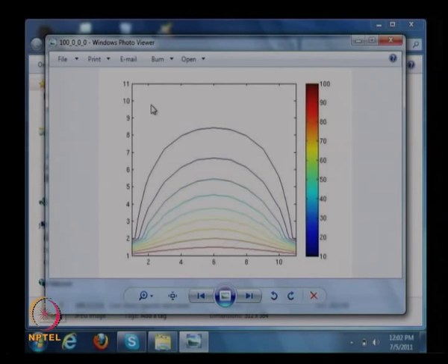So this portion of the slab has almost reached a temperature which is between 0 and 10, you have to look at what is the value here. Therefore the temperature is exponentially decaying in this direction. That means if you take this section and you plot the temperature distribution along y, it will follow the exponential decay which is picked up by this sinh n pi y by L.